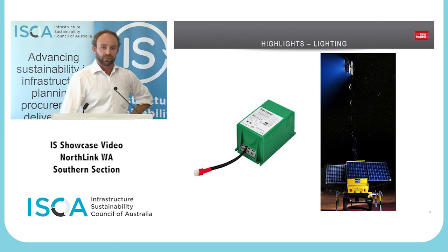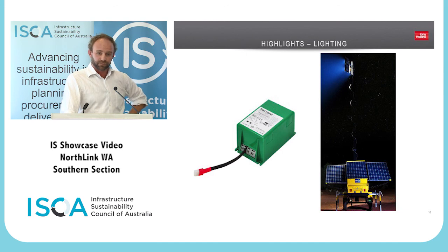There's a large number of light poles along that path, and the discussion carried on, and we realised that not many people will be using that path through the middle of the night. We didn't want to turn the lights off entirely for crime prevention reasons, but there was an opportunity to dim the lights. And so we were able to dim the lights through the middle period of the night, and we got about a 15% saving overall of energy from those lights. So that was a good outcome.